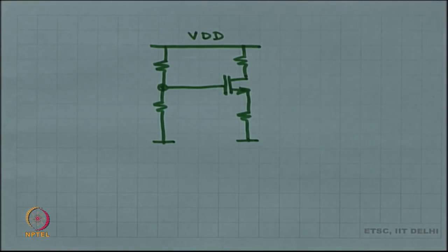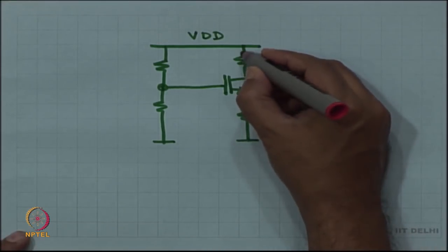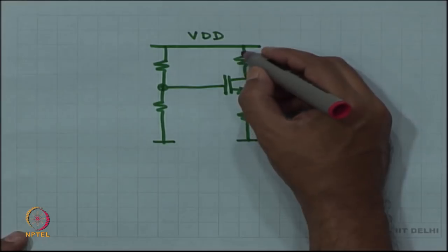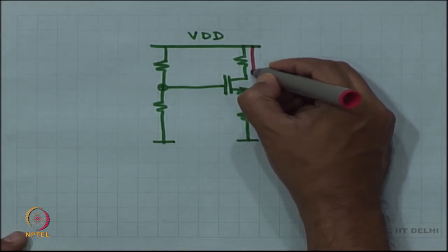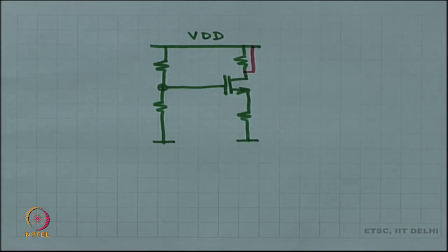And then we want to connect the drain to ground. Okay. So, connecting the drain to ground, one way to do it would be to remove this resistor altogether and short it, and that would be fine because it does not really change the DC operating point.